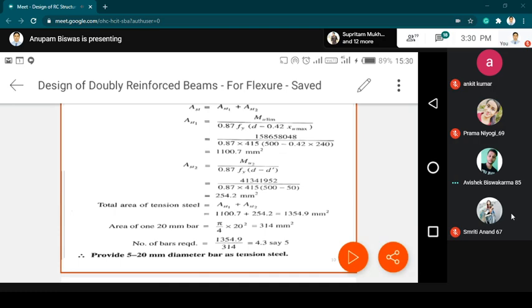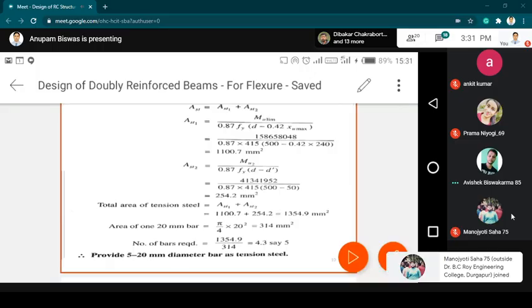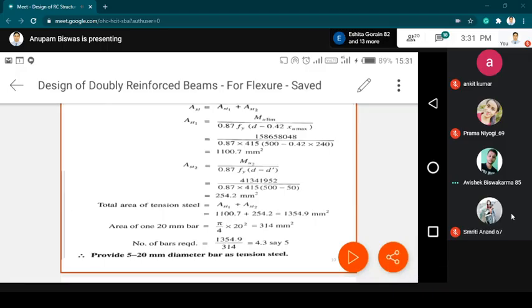नहीं हाँ मिनिमम तो लोगे. Suppose in general 16 mm or 20 mm bars are used, okay. For a suppose smaller section of beam, suppose 150 mm का width हो गया या 200 mm width हो गया और 300 mm depth हो गया, स्मॉलर सेक्शन, या फिर 150 mm width हो गया और 250 mm का डेप्थ हो गया, इस टाइप का सेक्शन जो होगा उसमें 16 mm का डाया दोगे तो हो जाएगा. लेकिन when you are considering higher section, suppose 300 mm by 400 mm, then obviously will require larger dia, 20 mm or 25 mm, okay.